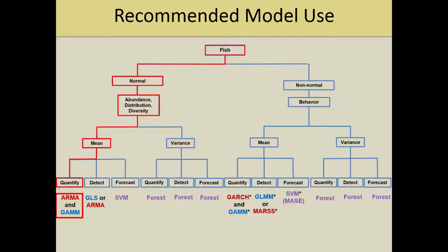No, absolutely not. What I would recommend, the strongest recommendation I make, is that there would be both surface and bottom surveys during the initial characterization, which would enable you to hopefully figure out what is dominating the site that you're looking at. It also enables you to get those scaling factors if you want to do a site domain. And then to think about, given the knowledge of what's out there, and often with these places being very, very dynamic environments with current speeds exceeding 2 or 3 meters per second. I mean, they haven't had a long history of sampling at all. You can't fish in there.